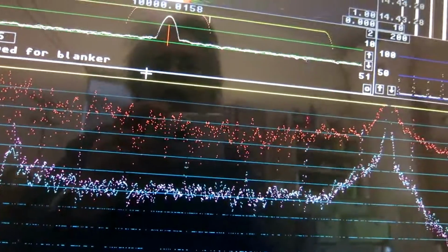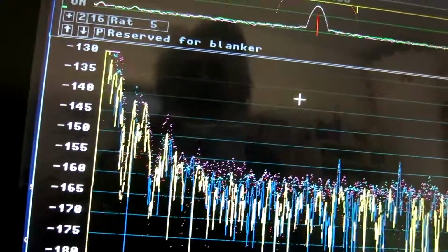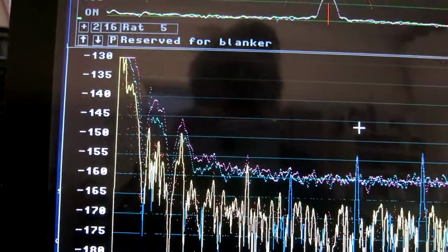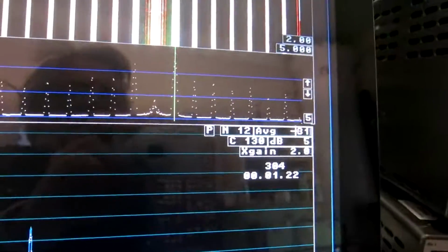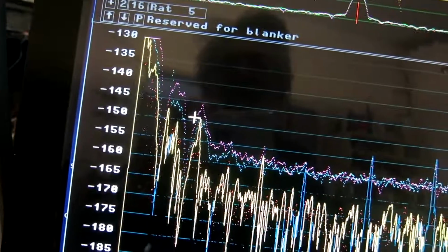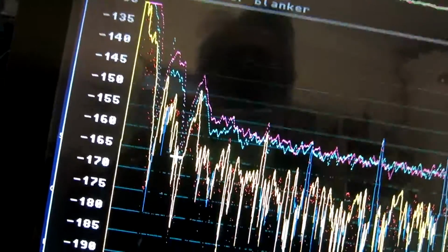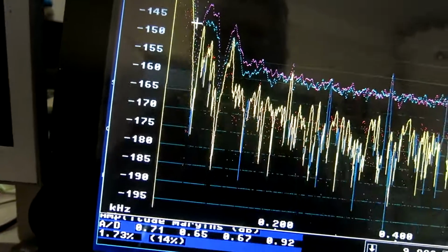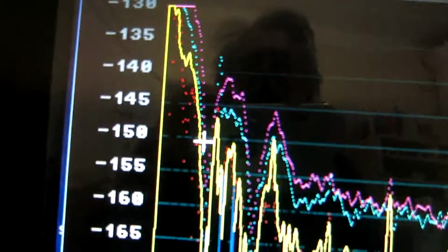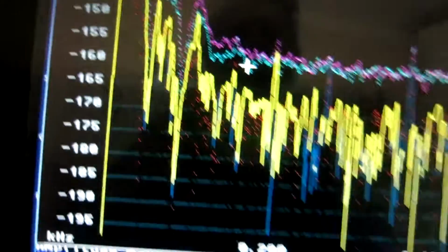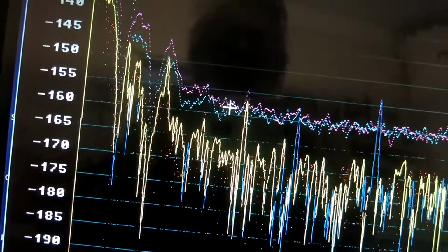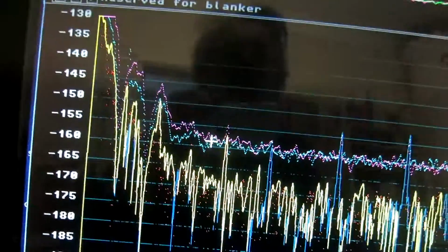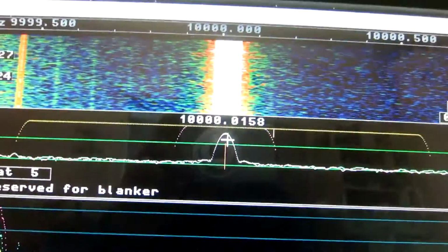So I can clear again the spectrum here and see if I can see that. And I don't have to look at the correlation. I just set a larger number of averages here, and then I can see the curve here, the detected FM signal. It has very deep minima at 100 Hz and at about 50 Hz. And I cannot say that I really understand it, but up to about 150 Hz I see some oddities. So it means that if I want to go to 1 Hz, I should set a filter bandwidth here of about 1 Hz.